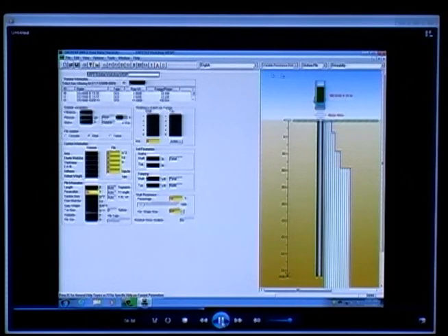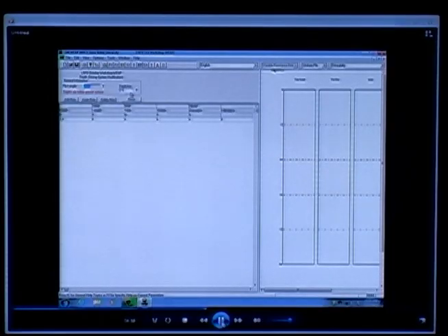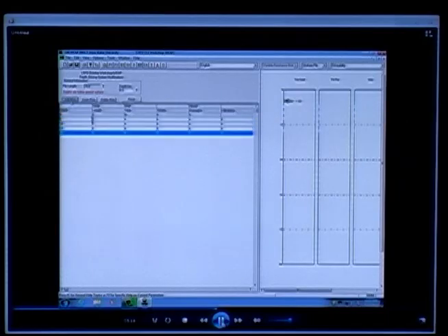Next, select View and click on Depths Modifier Input Form. This form allows you to perform analysis at your selected discrete depths. You can choose an increment. For example, a depth of 5 feet is chosen. Add rows for the depth down to the actual embedded pile length of 73 feet.